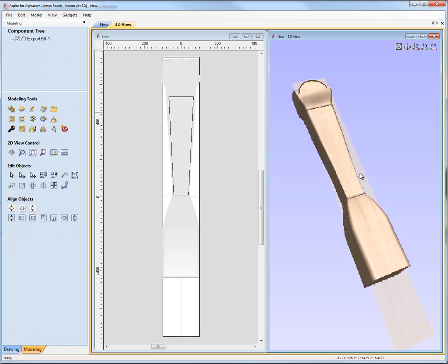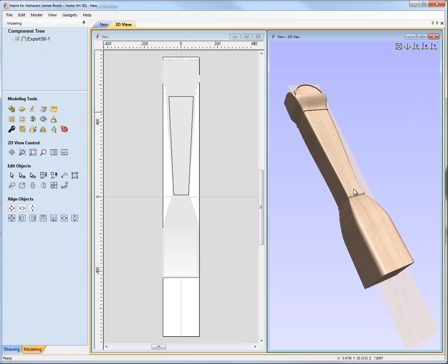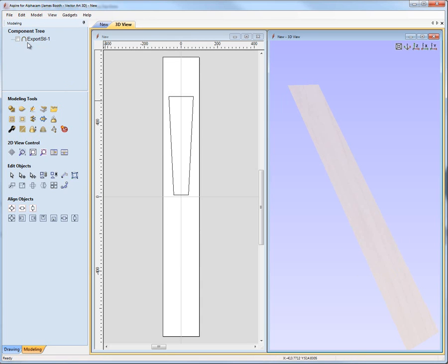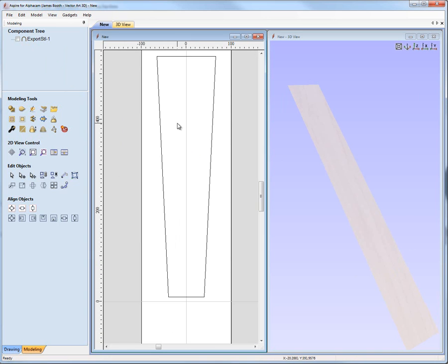this data in is so that when I've got my 3D models here in Aspire, they're going to sit on top of that and I'm going to be able to crop away all the rest of it, and when I export them back into AlphaCAM, that surface in effect that they're sitting on will put them in exactly the right place, because relative to the work plane they'll need that surface to sit on in order to put them on the face of the newel post. So at this stage I'll just switch off the model. We'll go ahead and concentrate on arranging the parts that we're going to import in Aspire here.